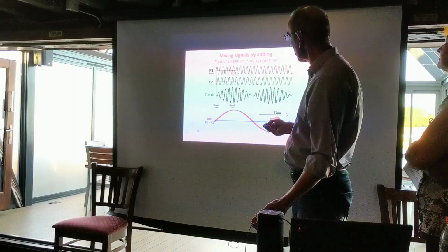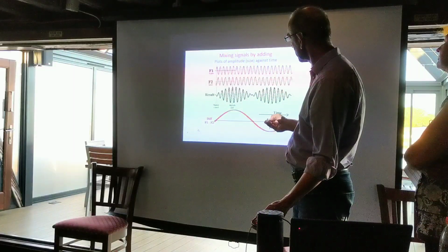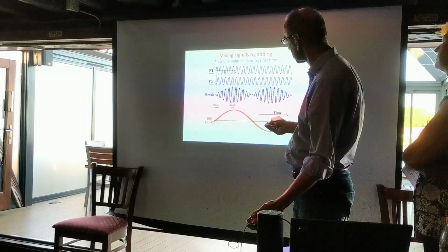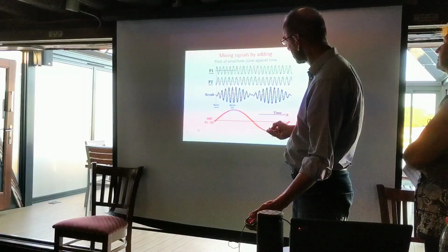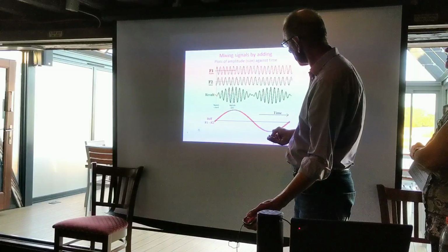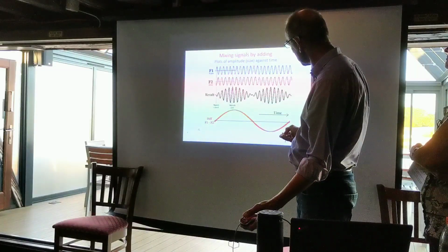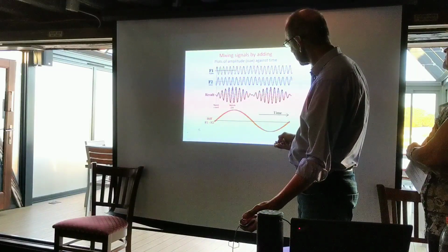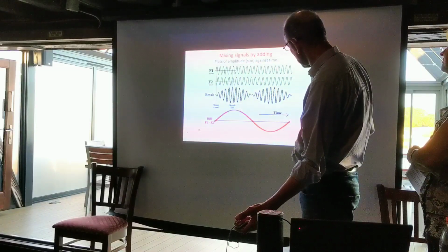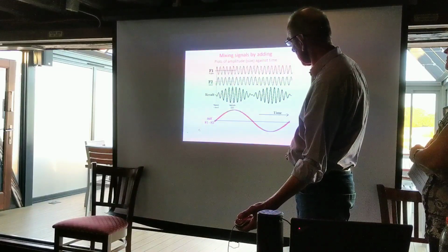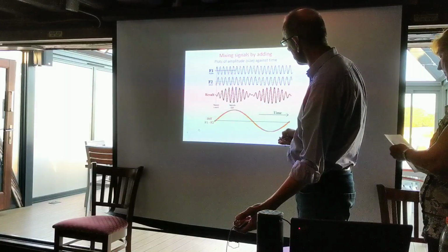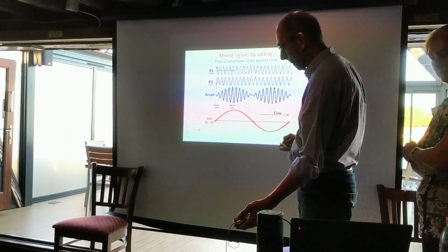A little bit further on, and these two slightly different frequencies, you can see this one is nearly at its maximum, and so is this one. So we get a signal that's twice as big. And as we go through this, adding them all up, you end up with a result that looks like this. And you can see, buried in this, there's a sine wave at a lower frequency. And the frequency of that sine wave is actually the higher frequency minus the lower frequency.